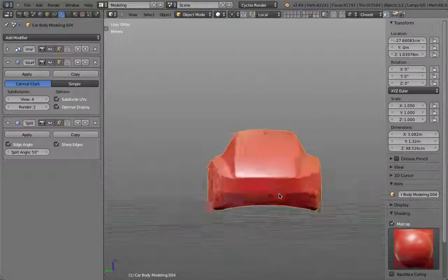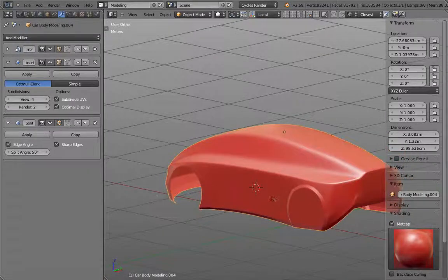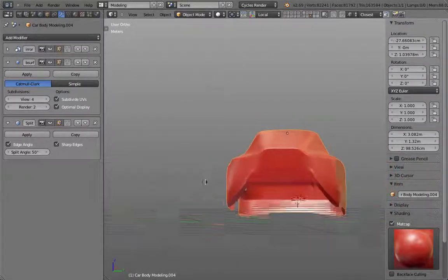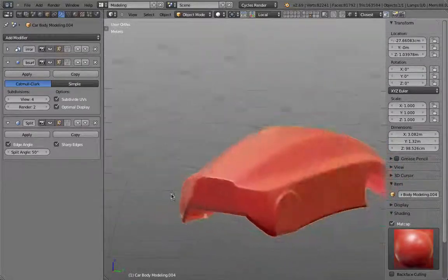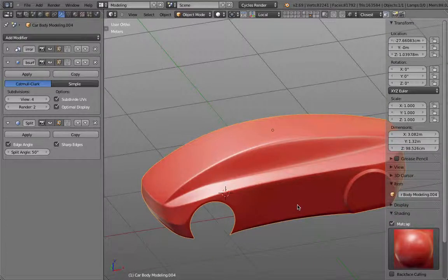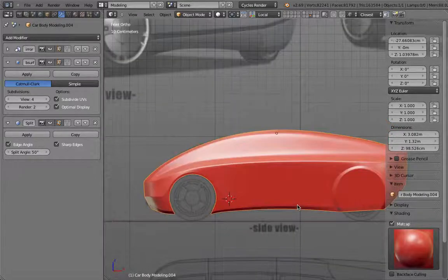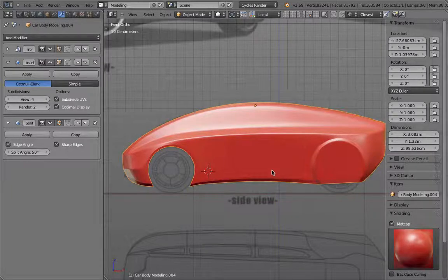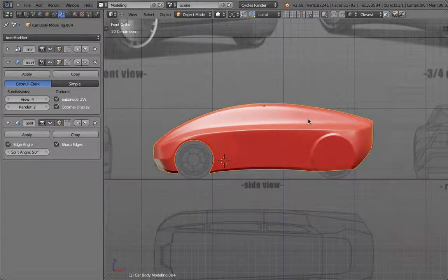And then quite quickly you can see I end up with the same result with those nice rounded corners or edges, and then again can pass a very simple polygon model to Fusion. It's a little bit more labor intensive, but at the same time you also have more control, because instead of having just a value you need to put in, I actually really manipulate that geometry and can have a little bit more modeling finesse applied to it.